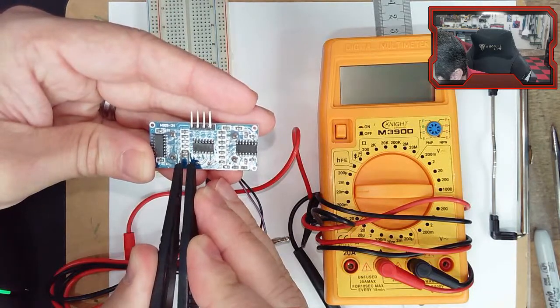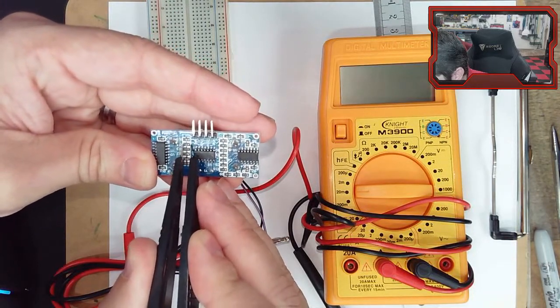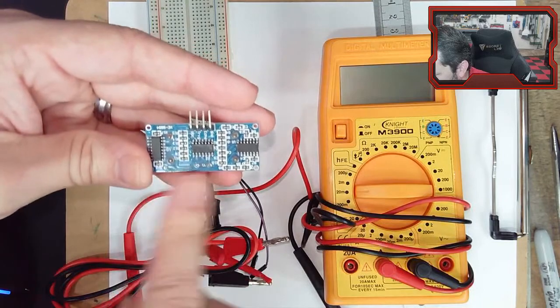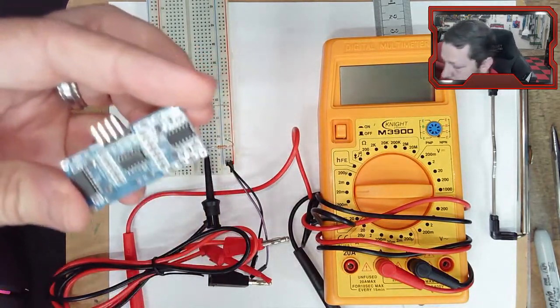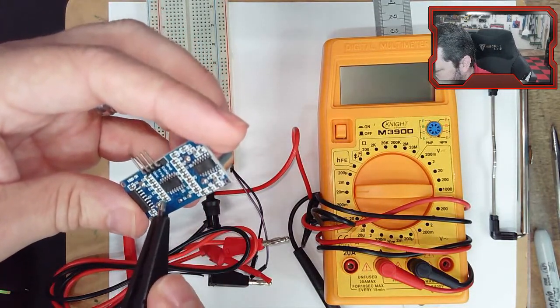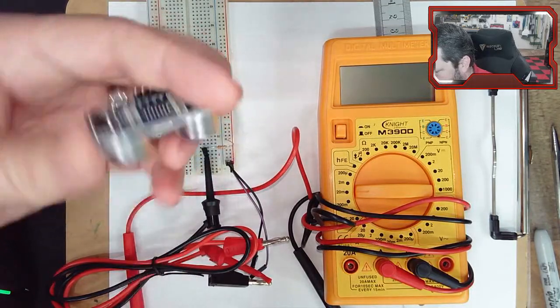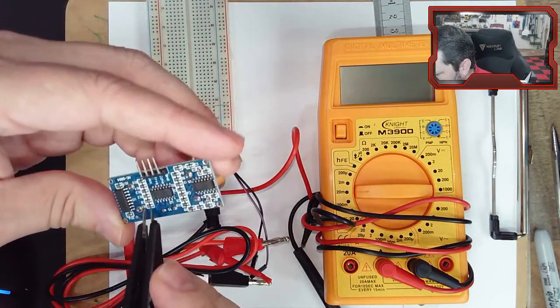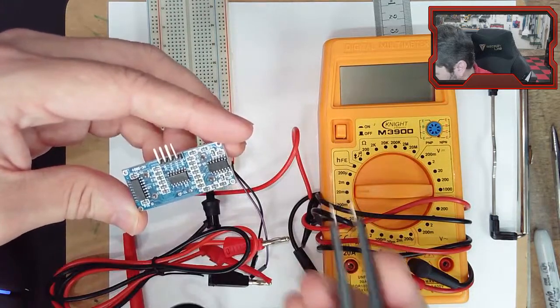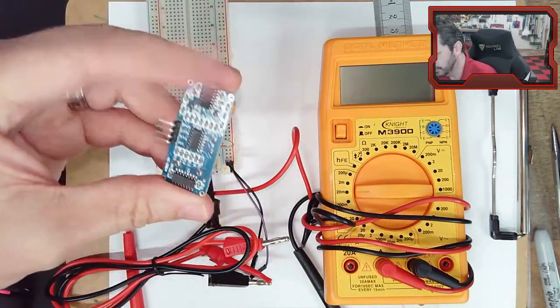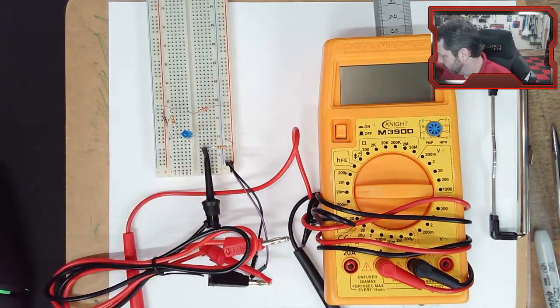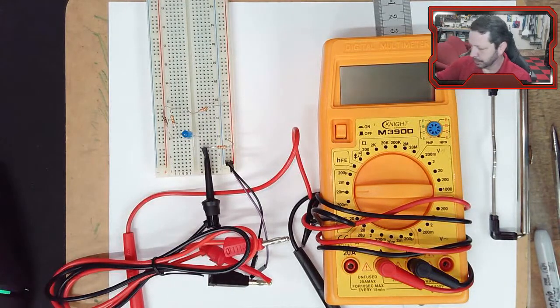Well, actually that's a capacitor. There's another resistor. I could measure resistance values. Now again, I'm measuring them on the board, so I might not get the resistance of that particular thing. I'm going to get the equivalent resistance at that point. But this little tool is kind of handy if you're using a lot of surface mount things that you're trying to measure on the board itself. I don't think we're going to need that for this class.